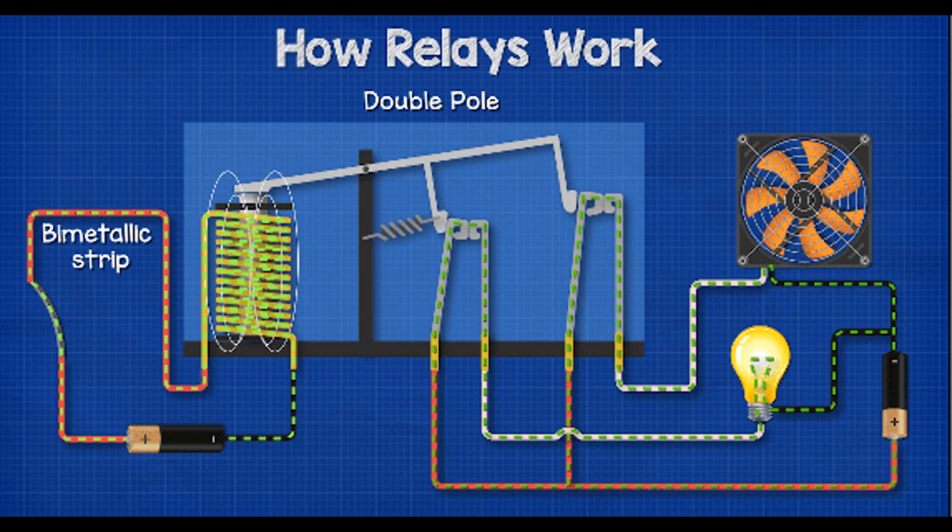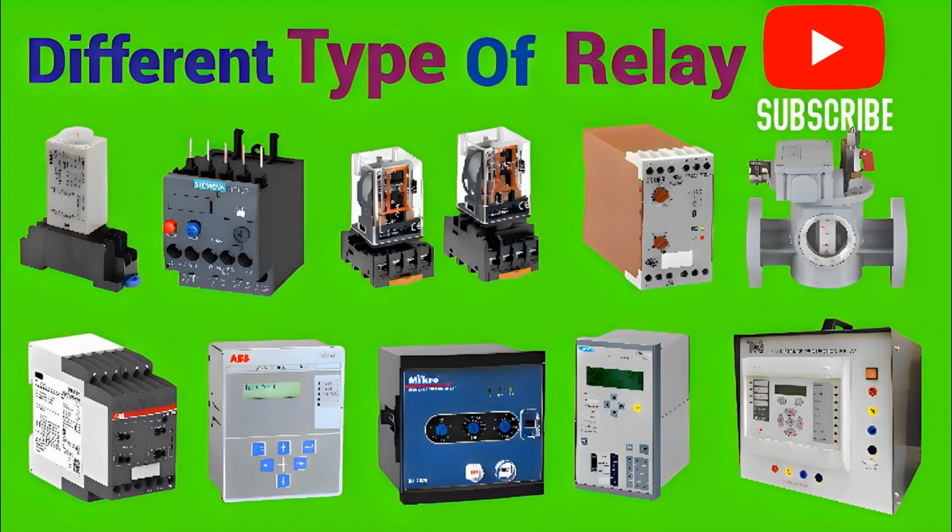Movable contacts are typically attached to an armature or relay switch mechanism and are designed to move in response to the application of a magnetic field or mechanical force. Stationary contacts. These contacts remain fixed in place within the relay and serve as the terminals for electrical connections. Stationary contacts are typically made of durable materials such as silver, gold, or copper alloys to ensure reliable electrical conductivity